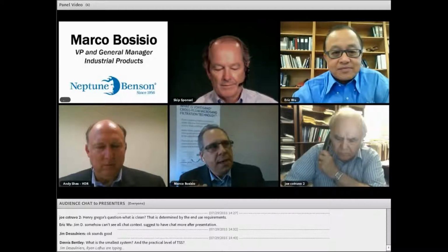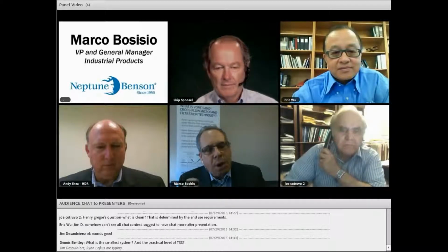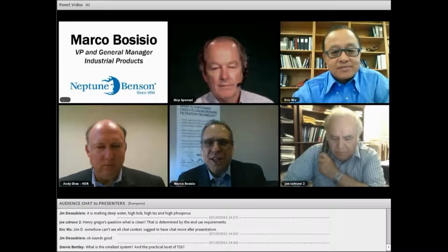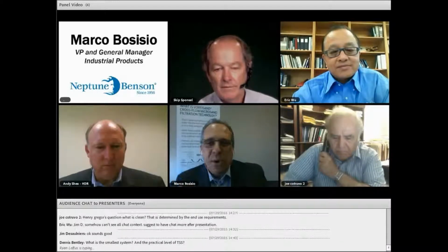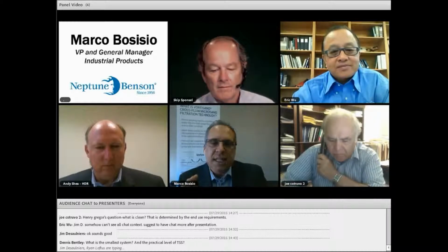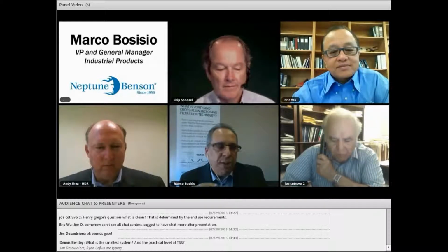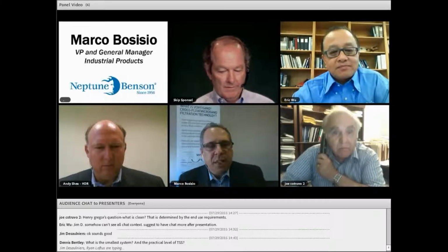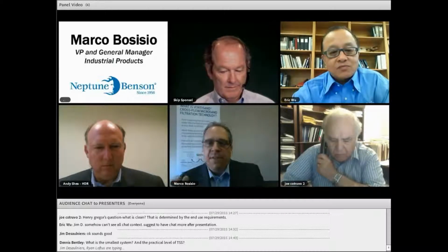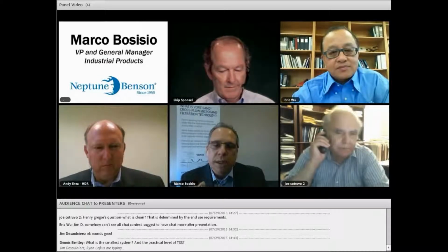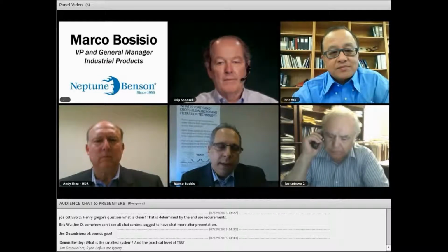It needs to be installed as a polisher, not a clarifier. It's not because we can catch anything that it should be thrown in. So it's difficult to say exactly how much TSS it will handle, because it's all relevant to how much backwash you want to see. So typically we're going to say 25 ppm is fine, but it also depends, of course, on the water quality you're looking for.